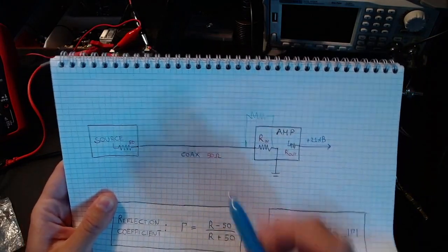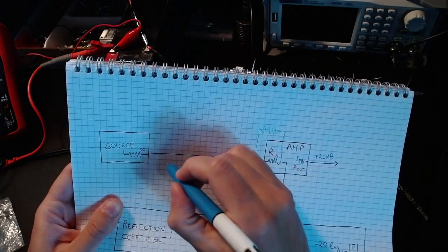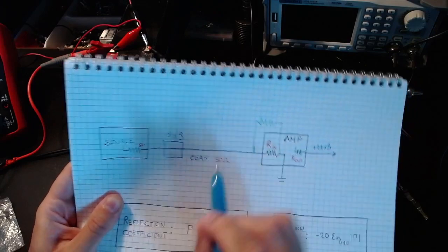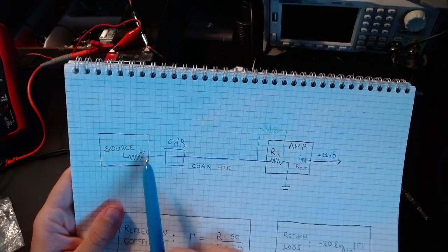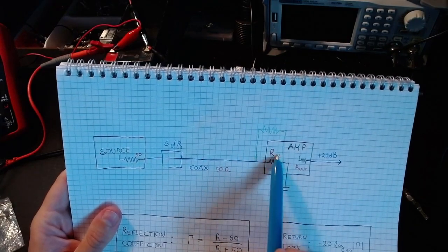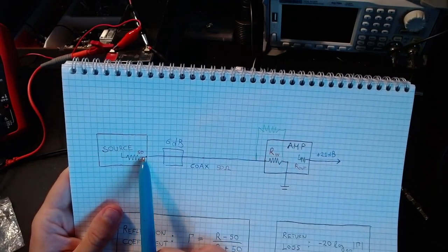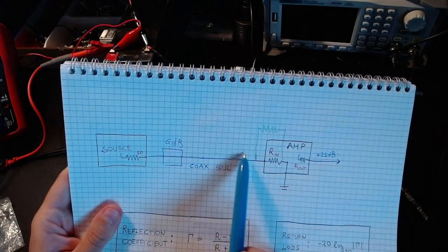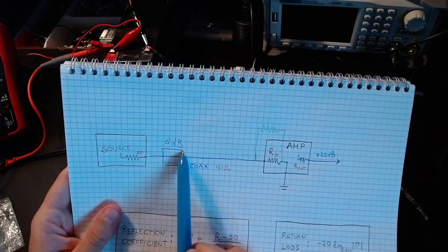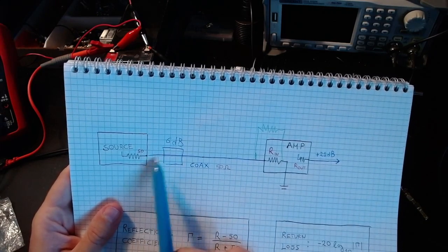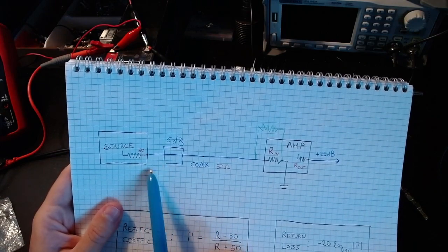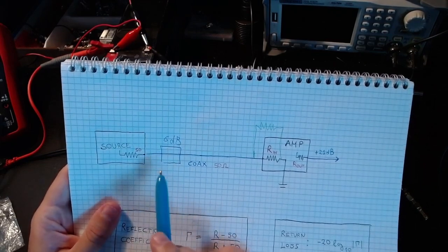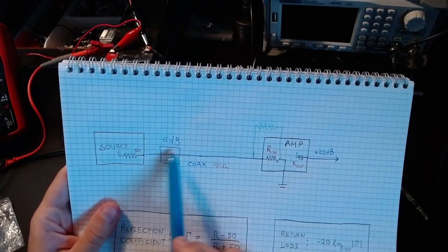Another simpler solution, if you have an attenuator, is to plug an attenuator here. For example, let's say a 6 dB attenuator. The idea is that no matter what the reflections are, the signal that comes out of the source gets attenuated by 6 dB, and when there are reflections, even if they are 100%, they will be attenuated by another 6 dB. So the source will always see the reflection at most at minus 12 dB down, which is acceptable. Okay, so that's a solution, but of course it's not great.